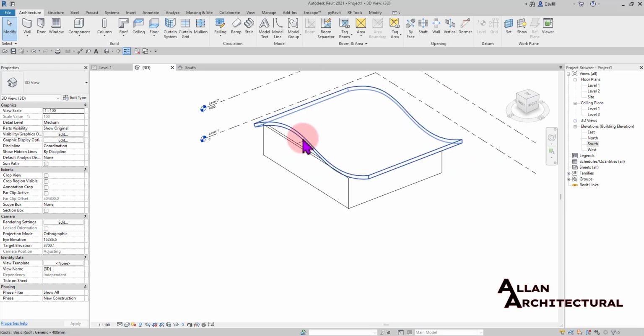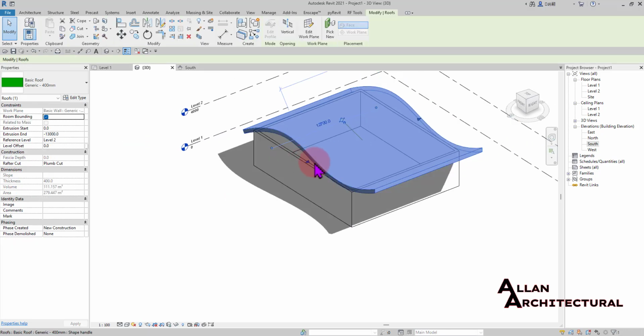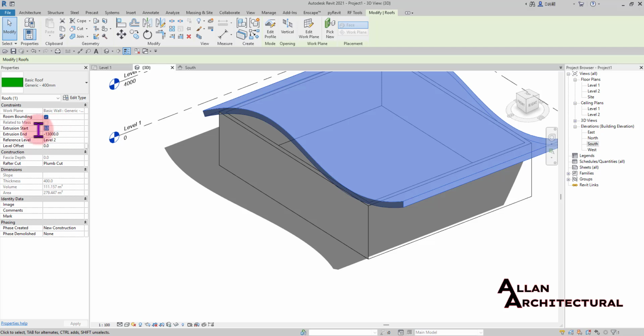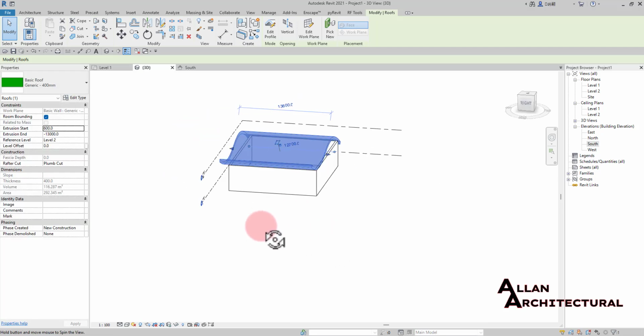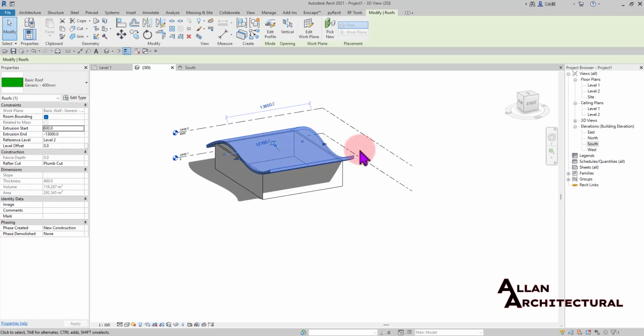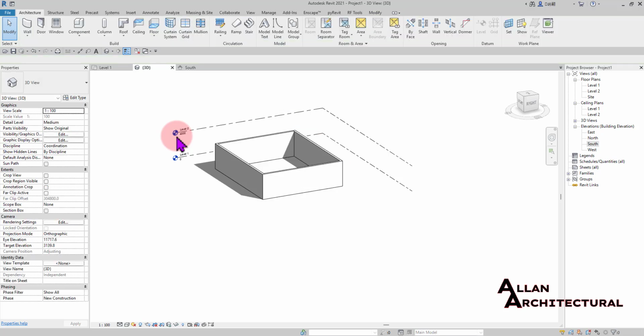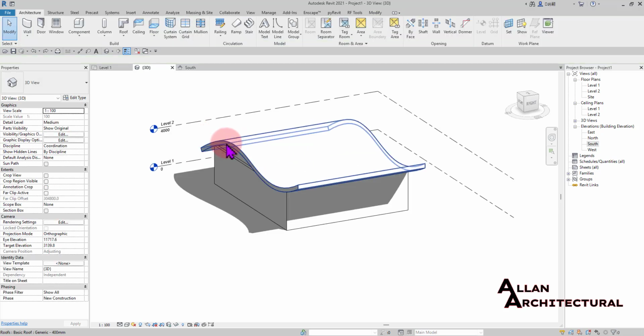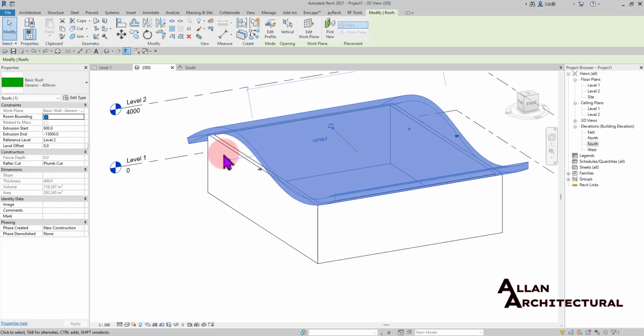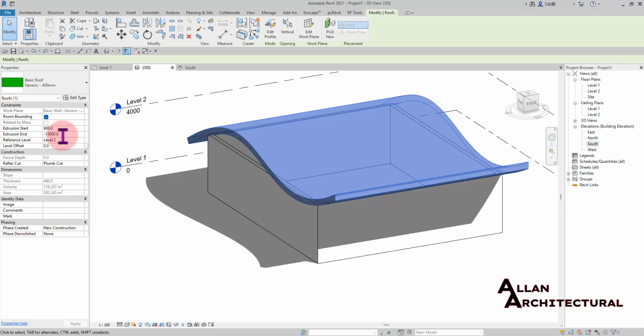We have that wavy roof in there. So with our start extrusion, we can come in here and give that about 600, and then you notice that extends 600 away from the wall in there. And we'll need to also do the same for that side in there. So you can go into your extrusion end in there, and you can change this to 9. Okay, just Control Z in there to bring back my roof. So I'm going to select my roof in there, and I'm going to change this to 9 in there.